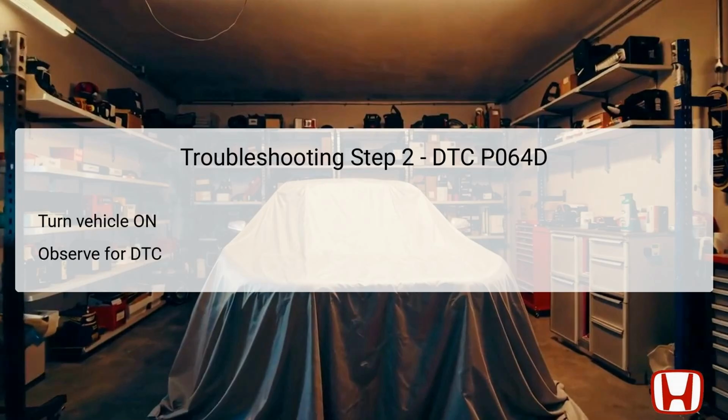Checking for the reoccurrence of the DTC will provide insights into whether the AF sensor or PCM is still malfunctioning. If the DTC returns, a more in-depth investigation into the mentioned components, including their connection and performance, should be conducted immediately. The recurrence of the code confirms an ongoing problem that needs to be addressed to ensure proper vehicle function.